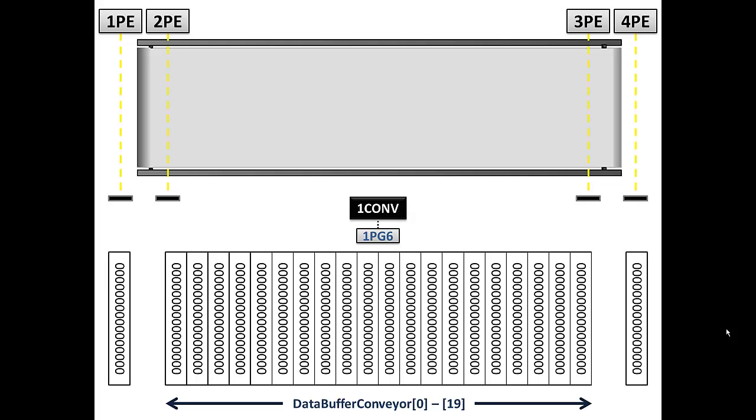This buffer conveyor could be multiple sections of 20 foot each being treated all as one great big long conveyor, with multiple cartons. Typically when you do that, you'll find a photo eye at the end of each section and the beginning of the next to make corrections based on any slippage.